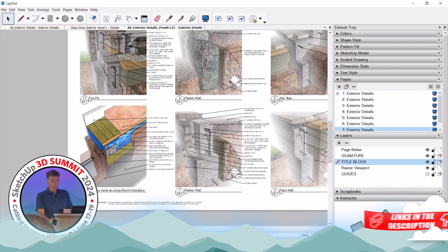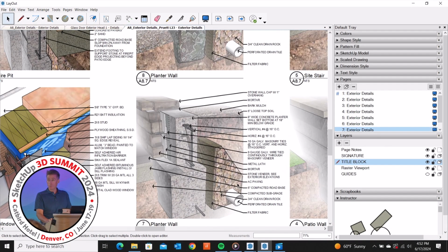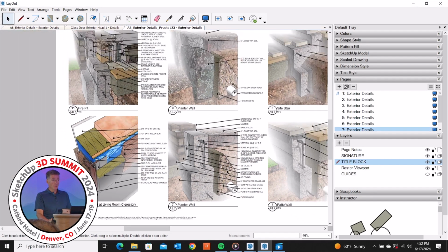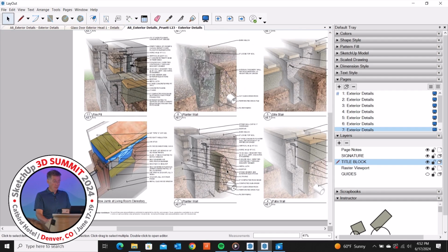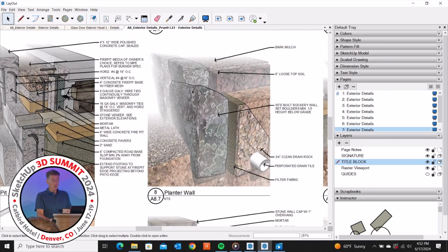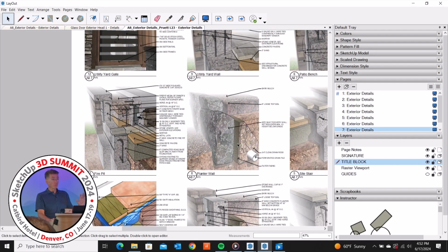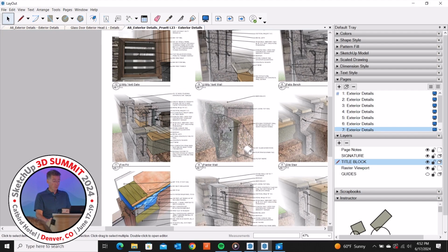We do on all of our walls, you'll notice drainage is a big issue where we are because of how much snow melt we get. So even the back sides of walls are always drained, especially on patios with pavers, because those can flood. And it's crazy to see, but it happens. And even this is a case where we have actually just a rockery wall, and we will back those with drainage behind it as well. If it gets really tall, we might do one up towards the top also.